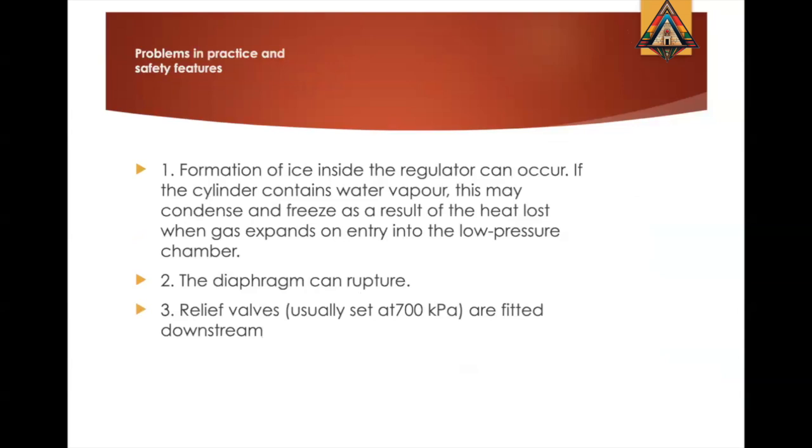The problem with those is that, especially with nitrous oxide, formation of ice inside the regulator can occur. If the cylinder has water vapor, this may condense and freeze as a result of the heat loss when the gas expands. The diaphragm that regulates anything can rupture, and that's why we have a relief valve usually set at